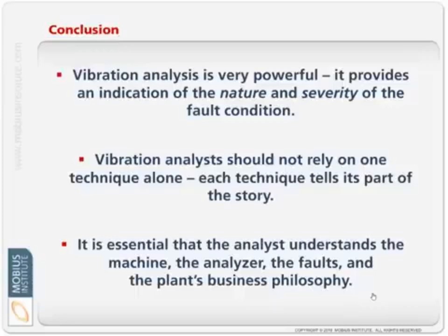But it is essential that the analyst understand the machine, the analyzer, the vibration measurement system, the failure modes as they're called, the fault conditions themselves, and the plant's business philosophy. Particularly when it comes to the idea of condition-based maintenance, but just understanding what the company's trying to achieve. On one hand, we can just say, we're just going to measure the vibration, see it change, and then say, okay, the machine needs to be taken out for repair or overhaul.